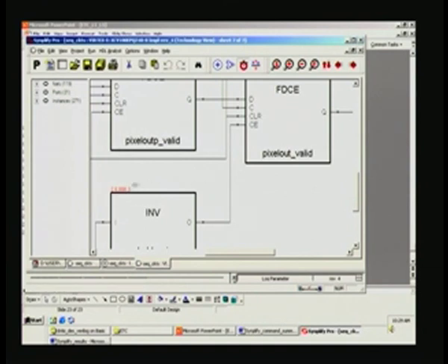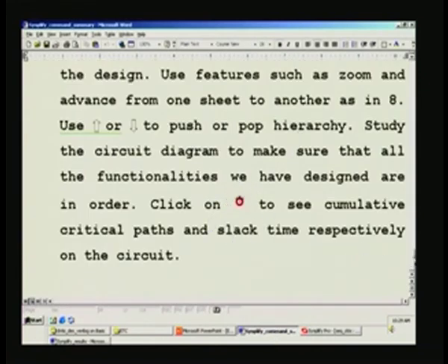If you see a negative sign somewhere, you can make it out. Unfortunately, no negative signs here. I am almost sure the first one is the actual delay, and at this point, although this is put here, it means this delay is at this point after the not, not at the input but at the output, and that will be cumulative. So, the entire path you can trace and find out where more time is being taken, and thereby try to optimize by inserting a register by way of pipelining. And next one is, and that is what we have seen here. So, this would complete the schematic viewing as such, and let us see what we have further.